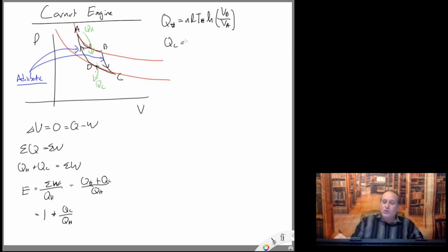And the Q cold is nRT, we could call it T cold, times the natural log of VD, my final point, over VC, the initial volume.